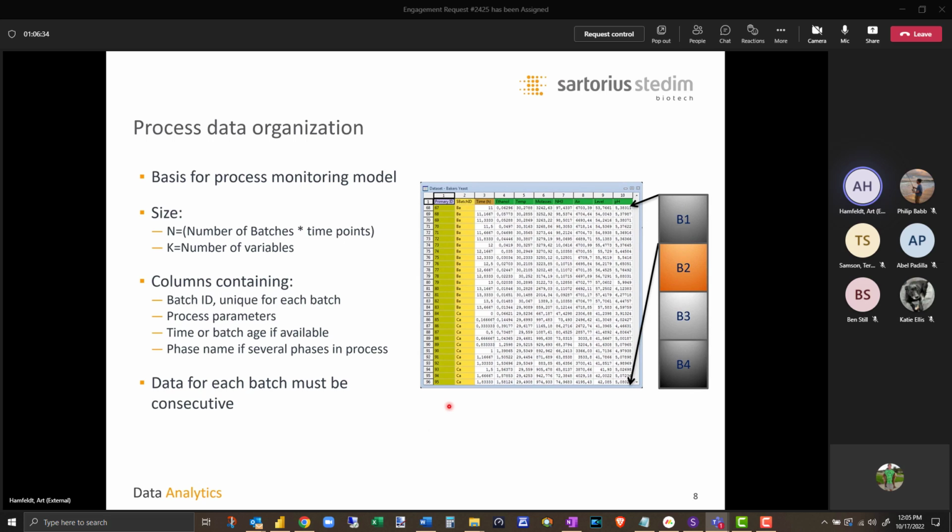Sometimes the issue is that batches sit in operator hold for hours. There are ways around that if you have event frames running. We do. Then that usually isn't a problem, because you don't normally use time as your maturity variable. You use elution, or a flow, as you say, a Q sum. If I Q sum a flow and the flow's halted because the operator stops something, the Q sum's not advancing, so in my model it's not advancing. It's just sitting there in the tank. The time could be going forever, but that doesn't matter.